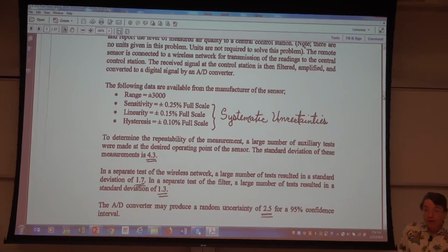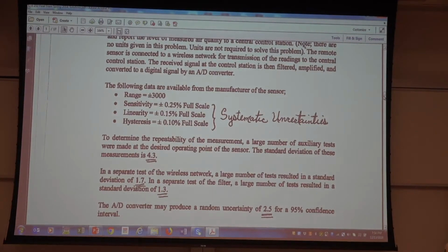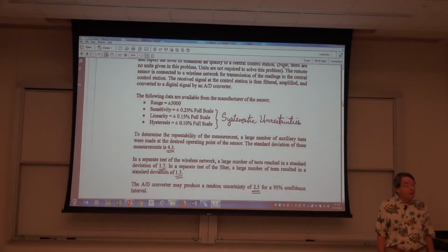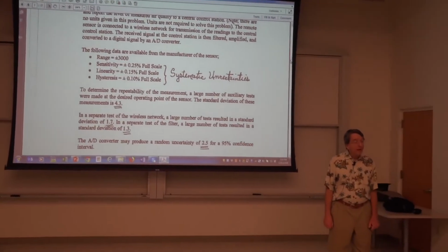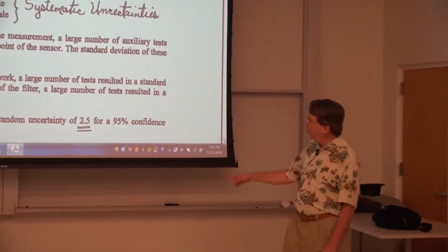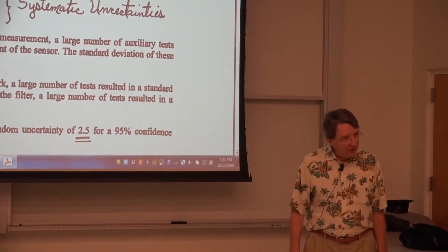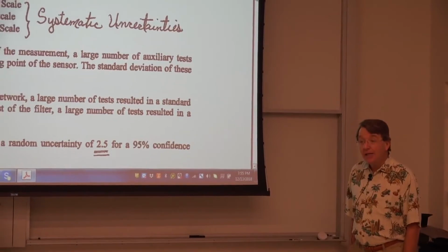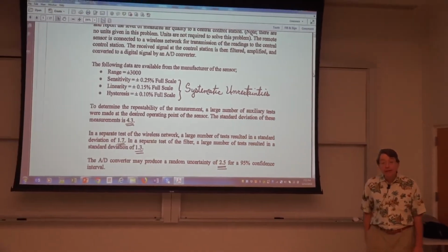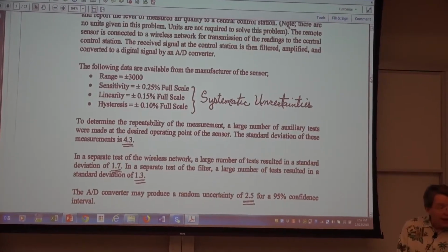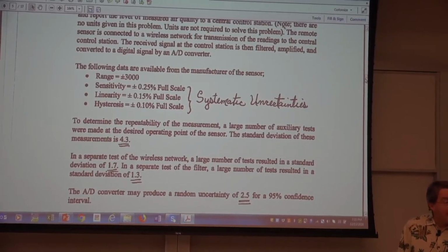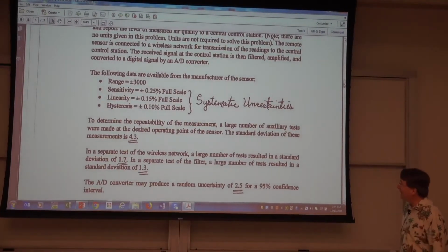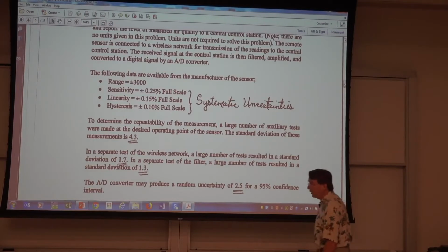So what we have here is another great question from Alexandra. Help me out. If I remember correctly, I think we call that the span, or sometimes just call the range. Okay, the range of possible outputs. But full scale is the max. And the sensor manufacturer typically states the error as a function of full scale, which is the maximum value out. So now we get 0.25% of full scale.